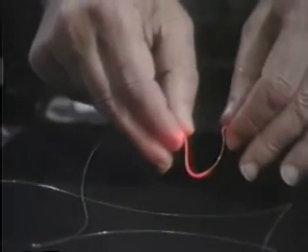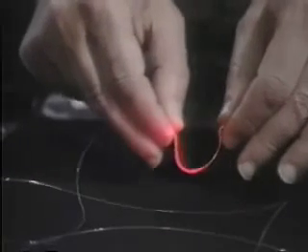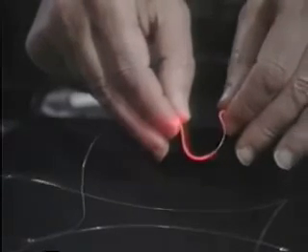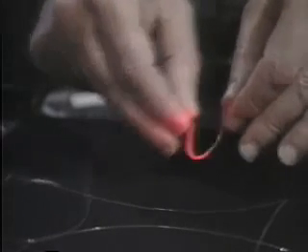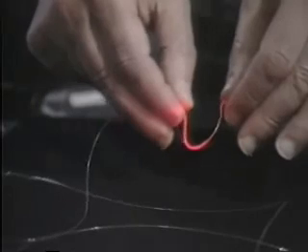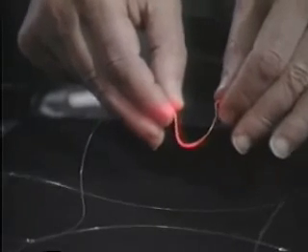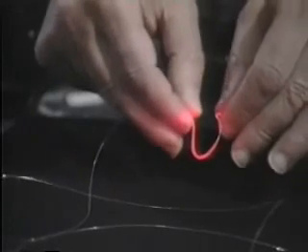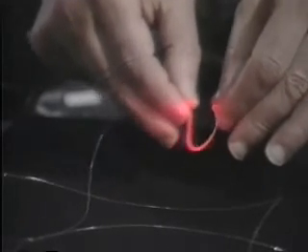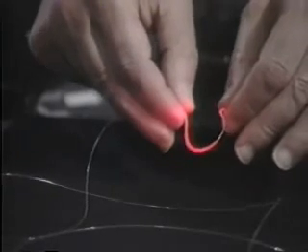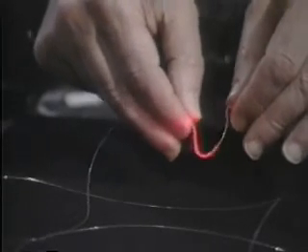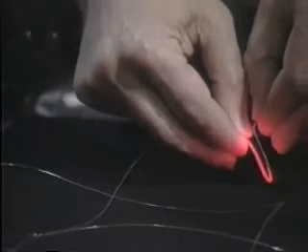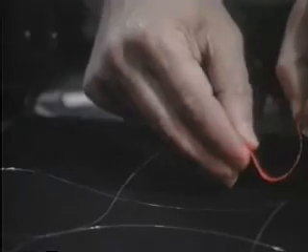For example, if you take the ray explanation, what you're doing is changing the angle of light with respect to the fiber, which means that if you're below the critical angle, then the light is no longer totally internally reflected and therefore gets kicked out. All right, so here it is. It's very dramatic. As soon as you put a little bend in this fiber, you can kick out a lot of light. In fact, there's the glow right here.